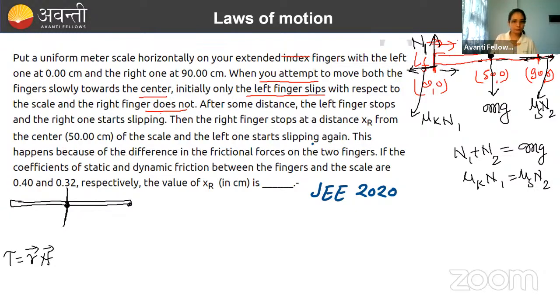Now, the friction force acting here is in this direction. Let me call it F2. And here it is acting in this direction. Let me call it F1. So if you extend the force F2, it will intersect the point around which I'm going to calculate the torque. So if your force is intersecting that point, then torque will be 0. Because here R is becoming 0.